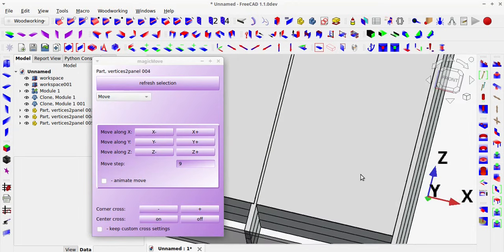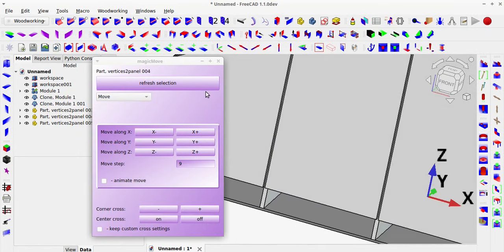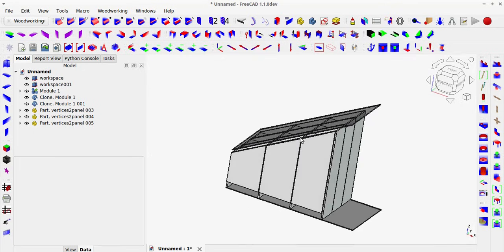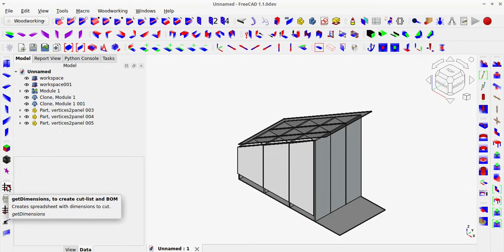Furthermore, they have the ability to detach the fronts, which isn't always standard with hinges, but for me this is very important because it simplifies any potential front replacement or even installation. The only drawback of these hinges is their limited adjustability, but once you've thoroughly tested the spacing in practice, you'll have no problems during assembly.